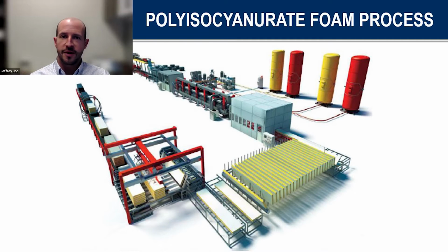I would say the most standard product out there from a polyiso standpoint in the industry is going to be your paper-faced, standard reinforced paper facer, oftentimes referred to as GRF or glass reinforced. That's a standard facer, widely used amongst the industry. The key component in that conversation being paper, right? There is paper, there is cellulose in that facer. That cellulose can absorb water. It can potentially lead to mold and bacteria growth if the water stays in there for a period of time and is unable to get out. So that is one typical drawback from your standard paper facer.